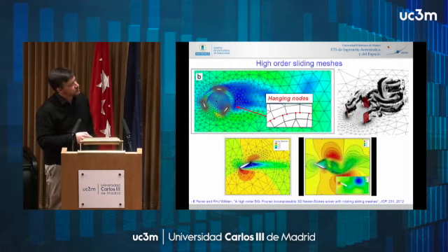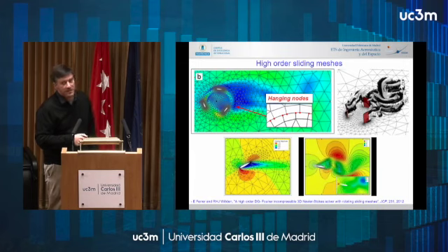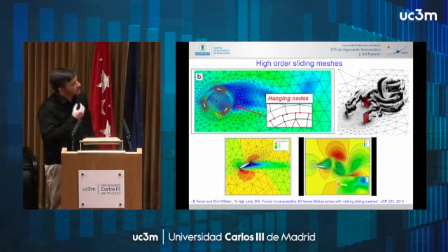So the contours don't even see the interface across where they have to go across, right? So this is a very accurate method, and it can be shown that it works for all polynomials, etc. So it works pretty well. We have to deal with hanging nodes. However, the problem is it's a bit costly, right? We have to deal with these interfaces and hanging nodes, etc.